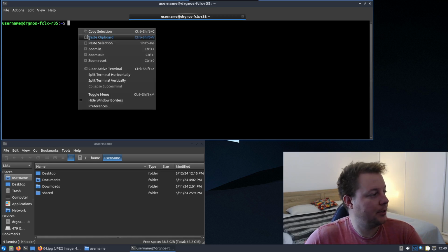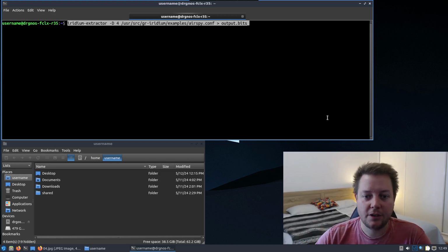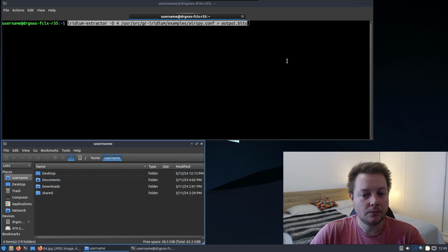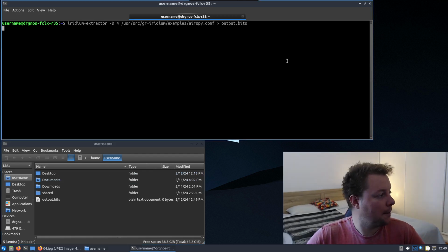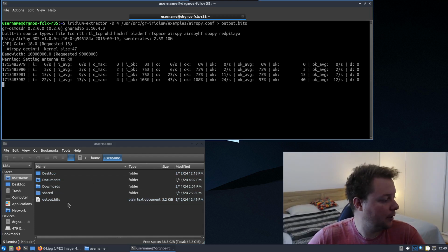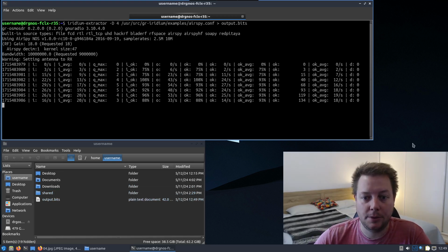And this command is going to instruct gr-iridium to tune my software-defined radio to roughly 1.6 gigahertz, and start recording Iridium data frames to a file in my home directory. So I'll just hit enter on that. And you'll immediately see a file being created inside my home directory titled output.bits.